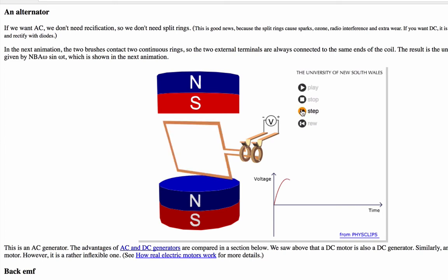And you can see as I step through, you can think of the top and bottom edges of the loop as actually cutting through the field lines that are running vertically. So we step it through, and at the moment, those same edges of the loop are still moving, but they're not cutting through as many lines. So the flux through the loop isn't changing as quickly. Then we get here, and we are now getting to the point where it's cutting through the most field lines, so the flux is changing most rapidly here. Where the flux itself is 0, that gives a maximum voltage.